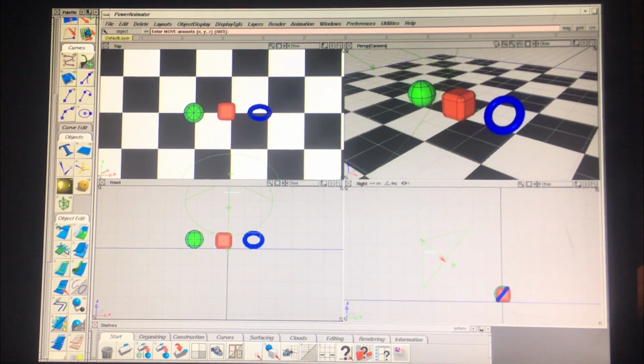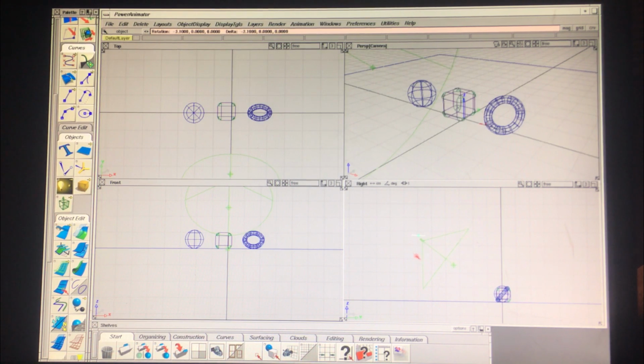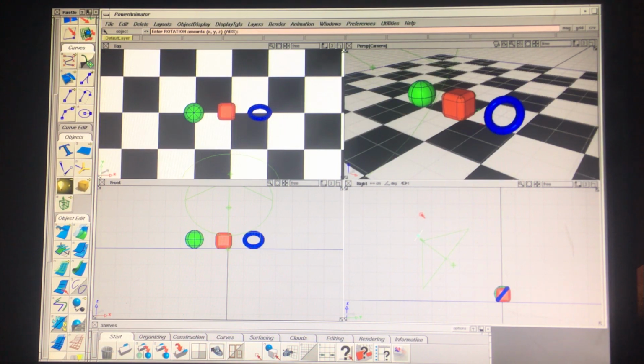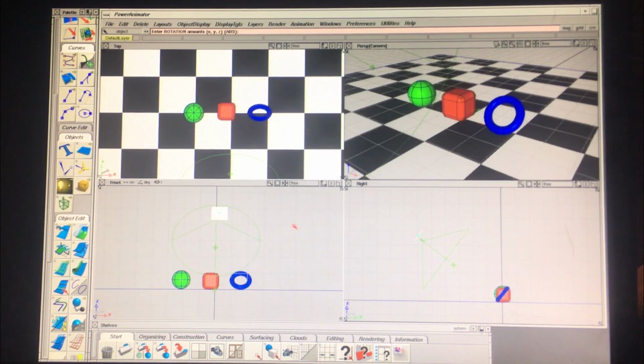Alt+Shift+M to move the view, and then we'll continue dragging this guy. Ctrl+Shift+M to get into rotate, and if I hold left click it should rotate on the X, which it's doing. Oops. Flatten that out, and let's see, Alt+Shift middle drag, see where we are. Oh, we're pretty close here.